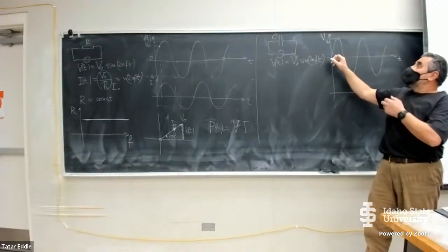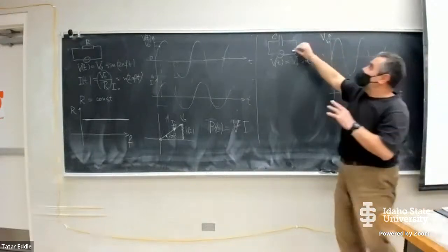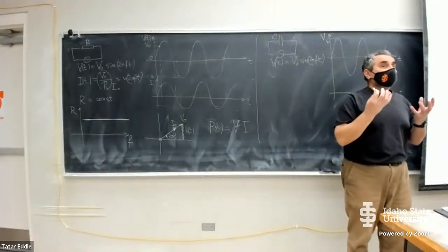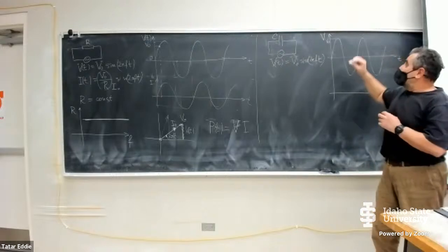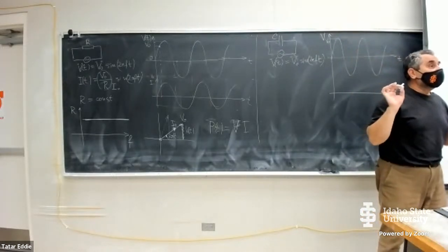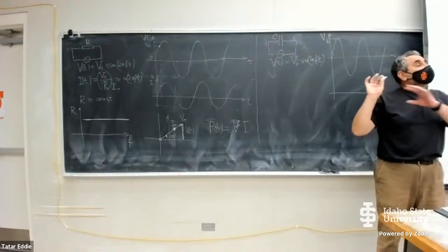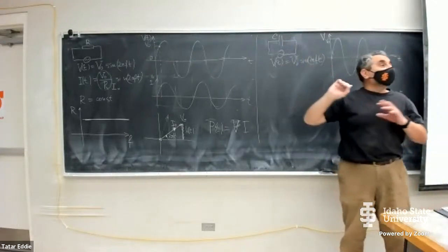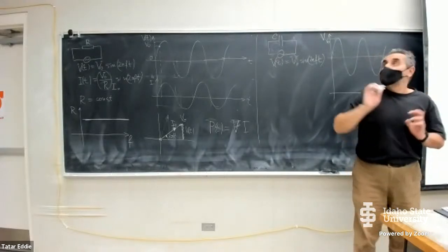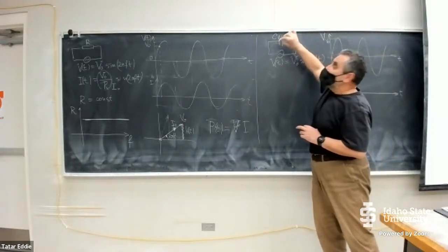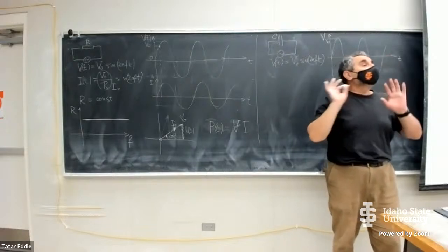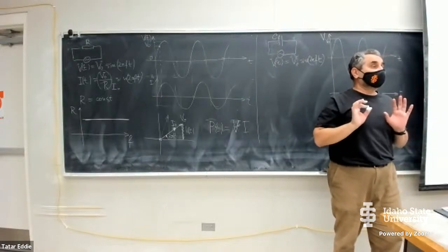And this voltage is going to drive charges and charge the capacitor very easily. A little bit later, when the voltage increases even further, the charges that are flowing, charging the capacitor, are going to have a more difficult time because there are already charges on the plate of the capacitor, and those charges are repelling the newcomers, the new charges.